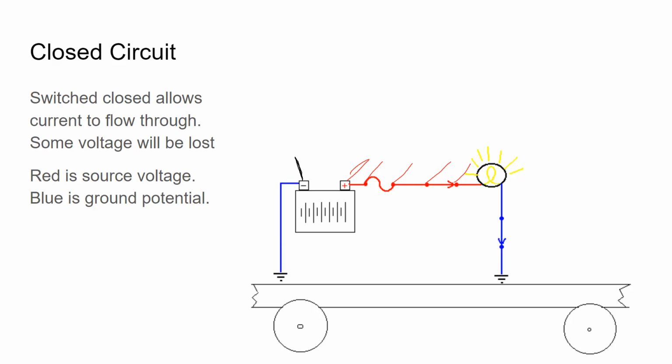If we take our black lead on the negative post of the battery, and then move it to this ground connection, the middle of the frame, some part of this switch over here, any one of these combinations for red, any one of these combinations for black on our voltmeter, we'll see a voltage difference of 12 volts.